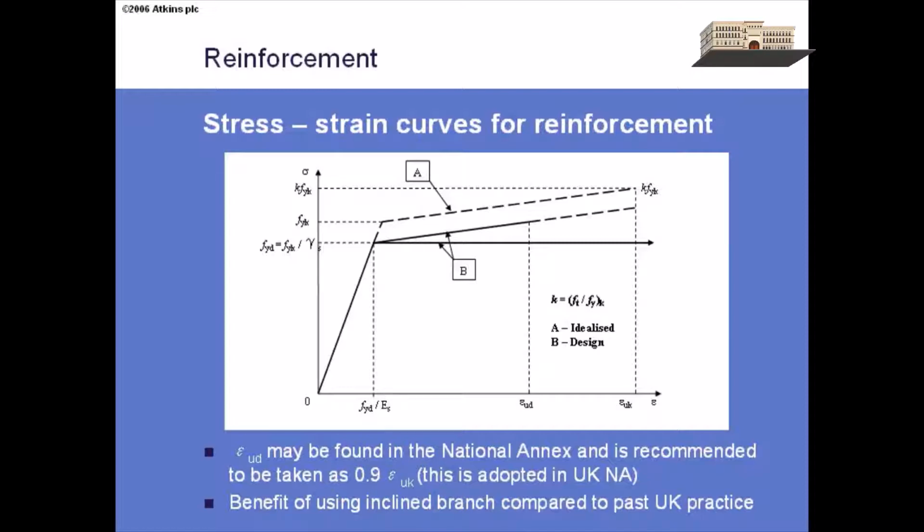Once again, if you're working for contractors, we're probably going to be doing all our calculations using software or something like that anyway. So there's really no point selecting the simple stress block. We may as well use the one with the rising branch because it will normally bring you some economy.